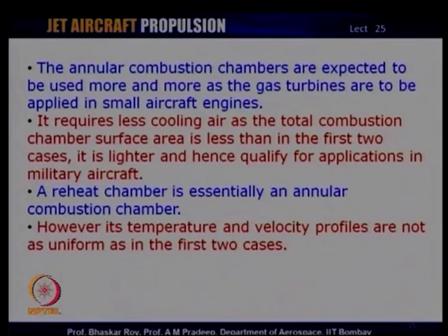It, however, requires less cooling air for the total combustion process, and hence it is lighter. It does not have all the weight of all those cans, and hence it is lighter, and it easily qualifies for application in military aircraft engines. Essentially, an annular combustion chamber is very similar to the reheat chamber, which people have been using for a long time.